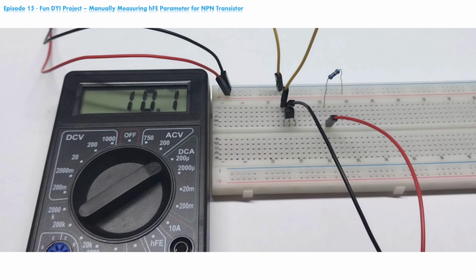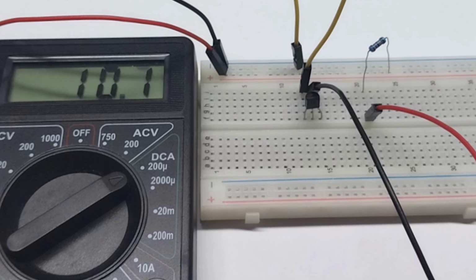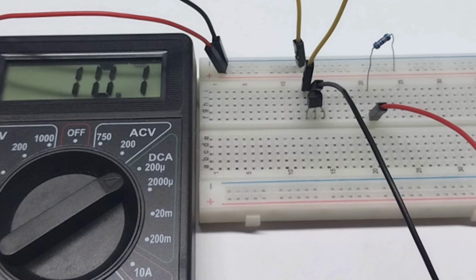Next, we will take the measurement for base current, by placing the multimeter between the base resistor and the base terminal of the transistor. We will set our multimeter on DC current settings, in the range of 200 microamperes, and take the measurement. We take a measurement of 10.1 microamperes. Also note that the collector terminal doesn't have to be connected to VCE in order to take this measurement. We are simply measuring the current coming out of the base resistor, and going into the base terminal.